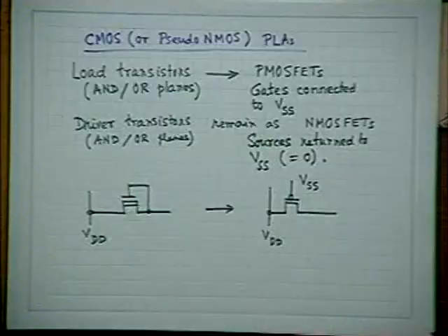In fact, for CMOS, the requirement is just on the opposite side. That means the PMOSes should have a little bit higher W/L, around 2, compared to the NMOSes, in order that we get good performance from the DC level operations as well as noise margin points of view. And therefore, here what you have to do is all NMOSes may be kept quite small.